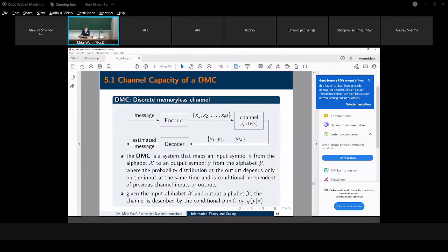So it's time discrete, okay? Time discrete. And today we switch to time continuous, and then you will see the results which you find in books, okay? So only if we have a channel, let's say, with a limited bandwidth, can we say we have a restricted symbol rate. Otherwise, we don't have any identification of a restricted symbol rate. Just the rate of the symbols here at the end determines the bit rate which is possible.